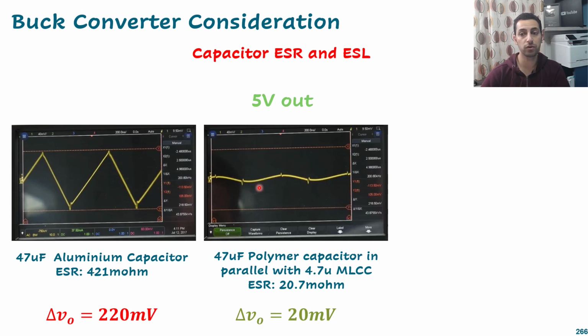So what is the voltage variation? Look at that. It's a very nice exponential growth for the capacitive voltage here and there. We have some notches there, and that's because of the switching and some parasitic capacitive components in the PCB itself, but it doesn't mean that we have a resistive or ESR impact here. So there is no ESR impact on this buck converter, because it doesn't copy what's happening here. We have some notches there and notches there. That might be from the inductance of that capacitor, or from the design of the buck converter and the PCB inductance itself and the Triacs inductance itself, okay?